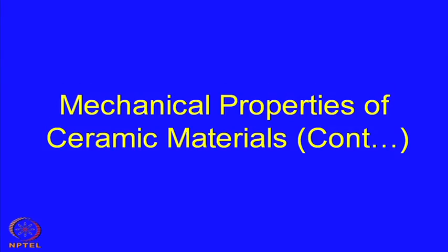Welcome. Today's topic is also the mechanical properties of ceramic materials, which we have been continuing for the last couple of lectures. In an earlier lecture, we have already discussed the different mechanisms of toughening ceramic materials, whether it is by fiber reinforcement or whisker reinforcement or simply by transformation toughening.